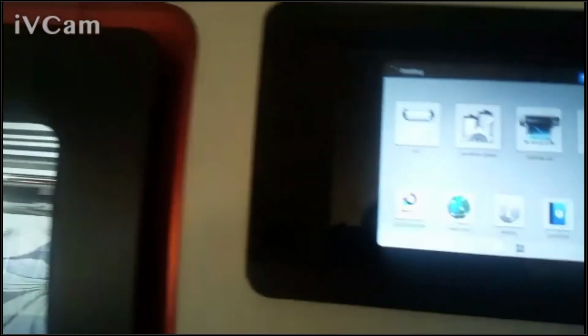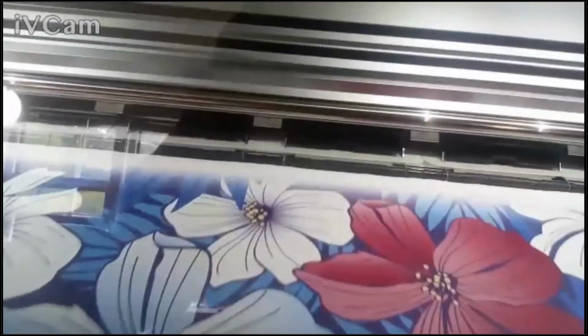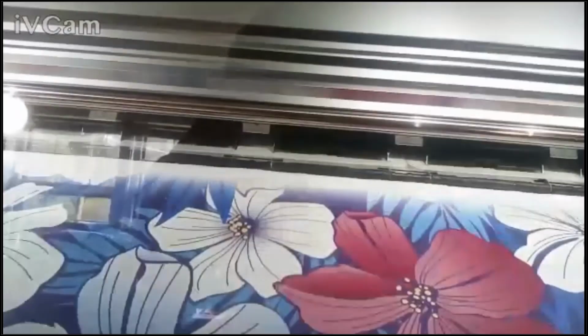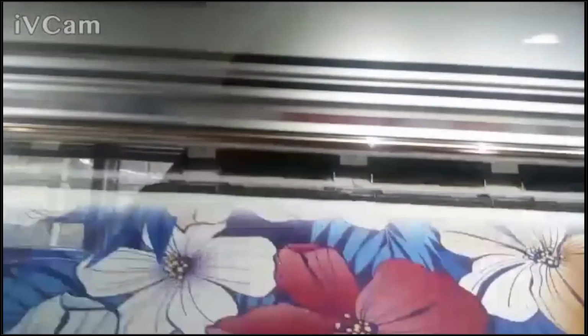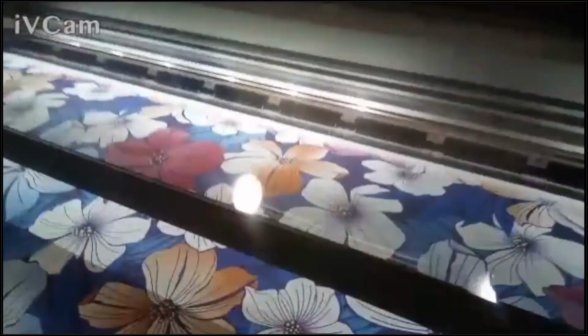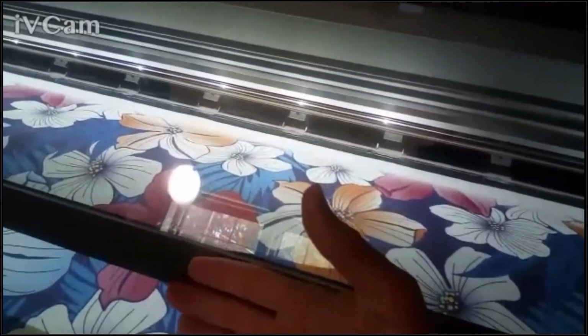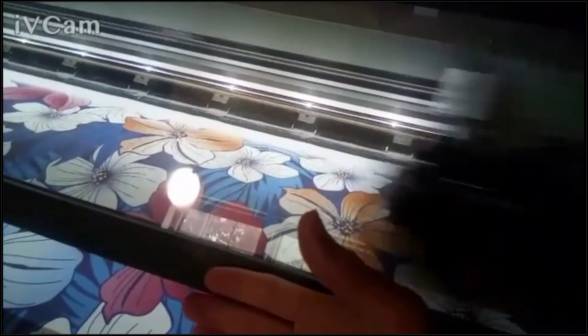So beyond that, what does this thing look like printing? This is a 4-pass. And I'm trying to get to a place where there's not much reflection. But you can see the speeds here as well. Now you'll see those black air vent looking things in the back of the print zone. Those are our diffusers, and they're blowing out hot air. If we were all on site in a demo, I would ask you to hold your hands here, and you can actually feel the heat coming out. So the heat's being applied in the print zone as it's printing.